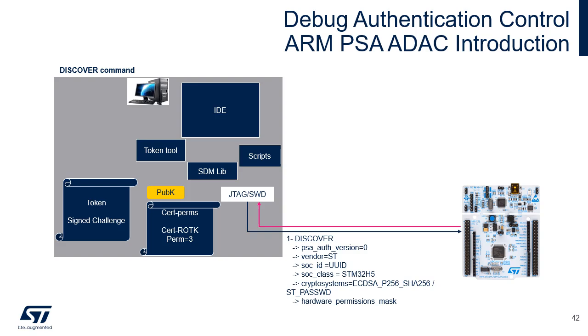The target can reply with any set of values that's equal to or a superset of the requested values, excluding any value unavailable on the target or not recognized by the target. If a requested ID list is not included, the target must reply with all available values. Use of this command is optional and is not part of the required authentication command sequence.